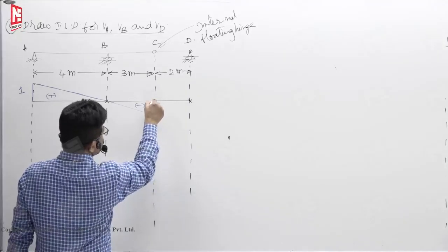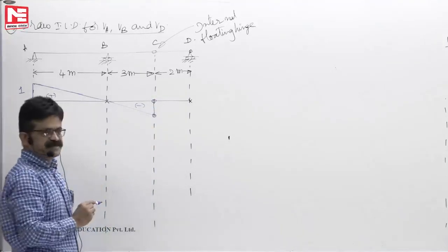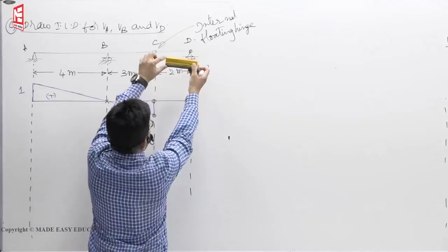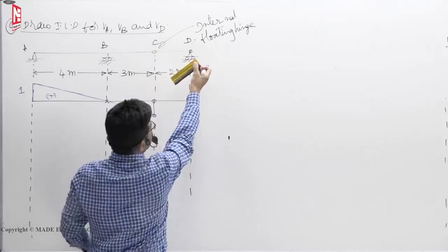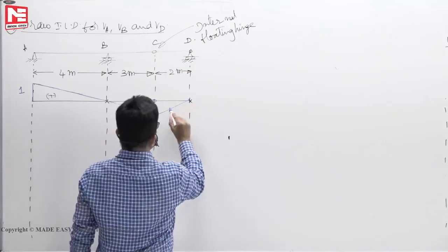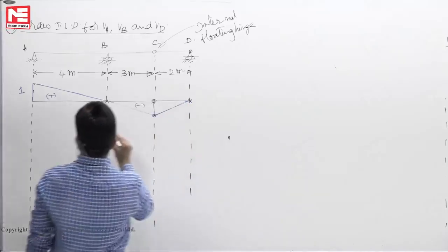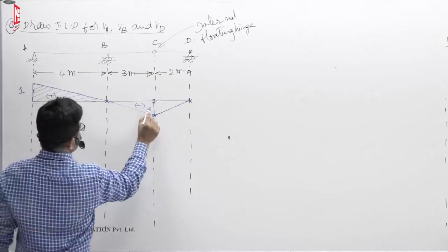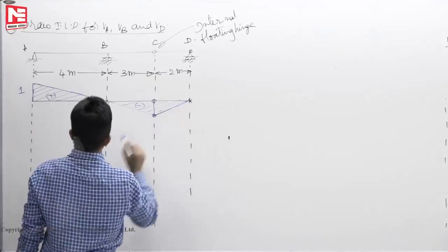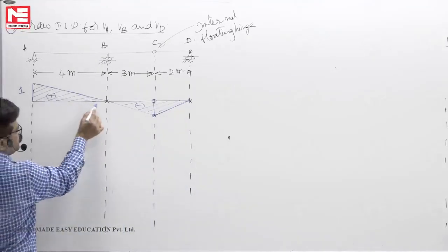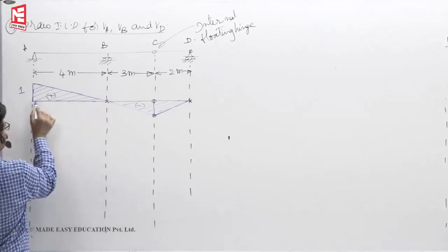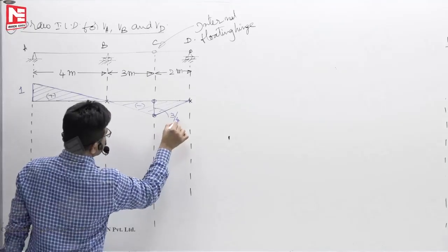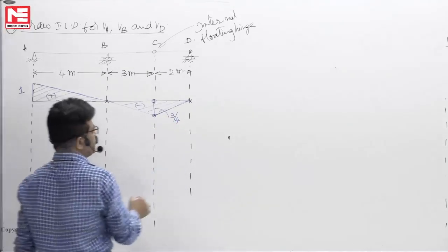There is a floating hinge here. It permits the downward displacement. So a straight line came. Now, C is going down, then the CD member will simply come down like this. Okay. So positive, if a beam goes above the reference line, it is positive. If it goes below, it is negative. Now from linear interpolation, you can find the ordinates. For 4 meters it is 1, for 3 meters it is 3 by 4 or say 0.75.